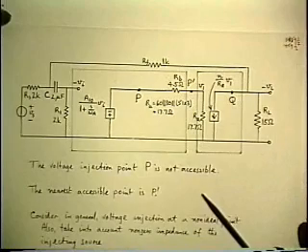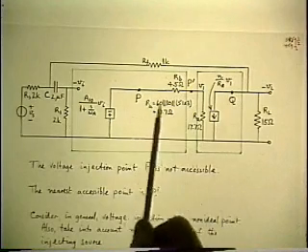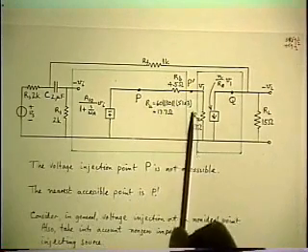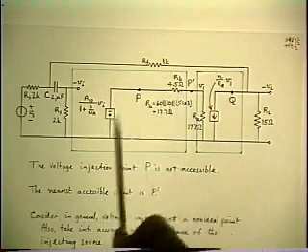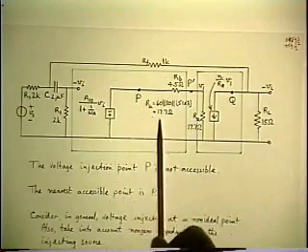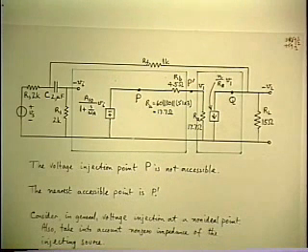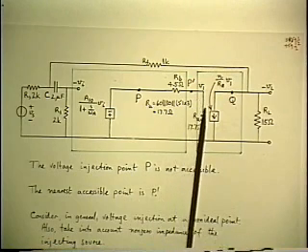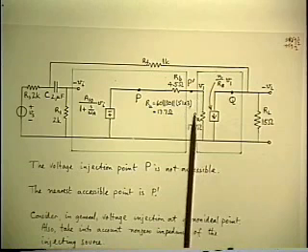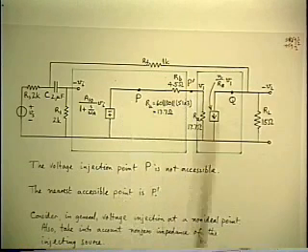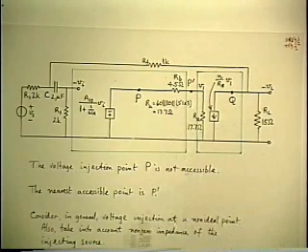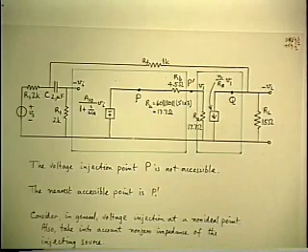So in this case, I could put these green boxes around here to indicate that you can't get inside that box. The output impedance of the driver is buried inside and you can't get around it. So sooner or later, we have to face the fact that we're going to do the injection at a non-ideal point. So let's see what happens. Obviously, the thing you do is get to the nearest possible accessible point. But still, we have to allow for the fact that there's going to be a non-zero impedance. So let's look at that question now.